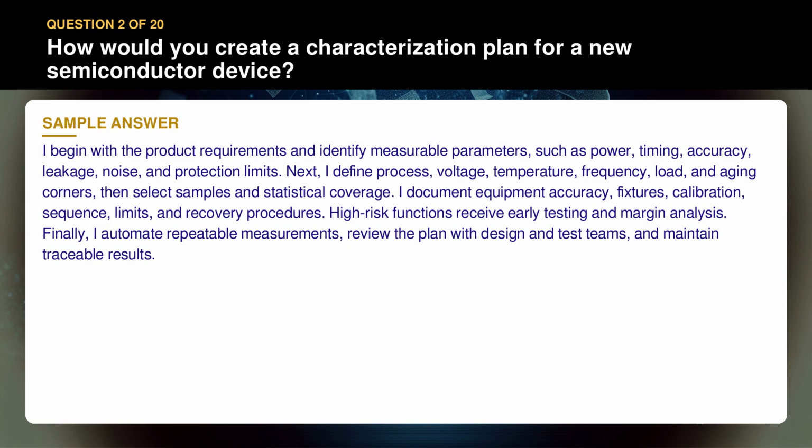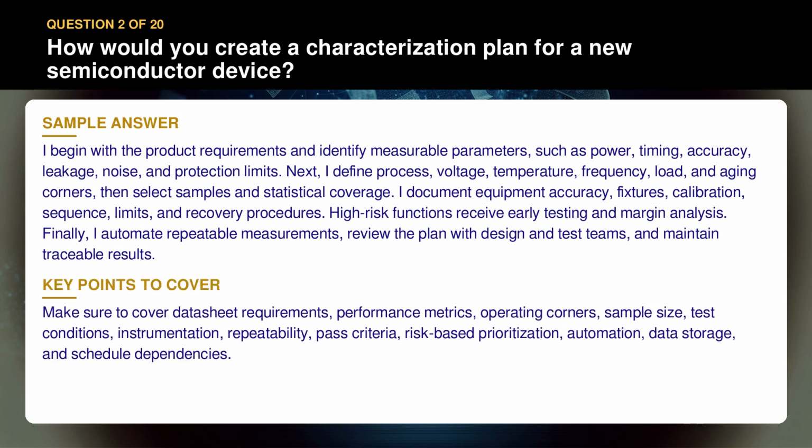High-risk functions receive early testing and margin analysis. Finally, I automate repeatable measurements, review the plan with design and test teams, and maintain traceable results. Make sure to cover datasheet requirements, performance metrics, operating corners, sample size, test conditions, instrumentation, repeatability, pass criteria, risk-based prioritization, automation, data storage, and schedule dependencies.